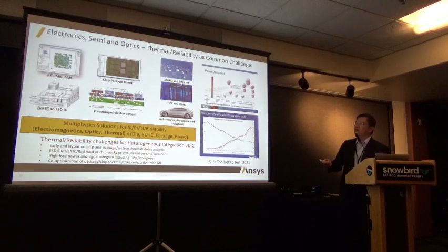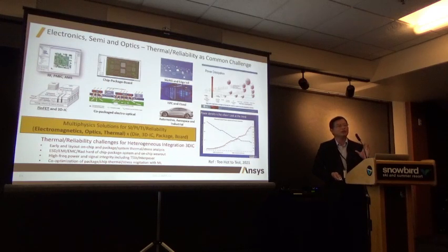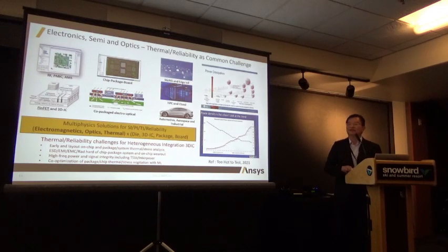Here are a couple of challenges for 5G and 6G combined with gallium nitride or the digital domain: how to handle analog mixed signal design combined with digital design in high power. That's one challenge coming from the 5G, 6G industry. The other challenge, coming from HPC and cloud, is that power continues to rise above 300 watts, 400 watts, or more than 10,000 watts for a Cerebras system. And for automotive, the focus is on aging and reliability, which needs to survive at least 15 years. So we can see the power continues to increase.